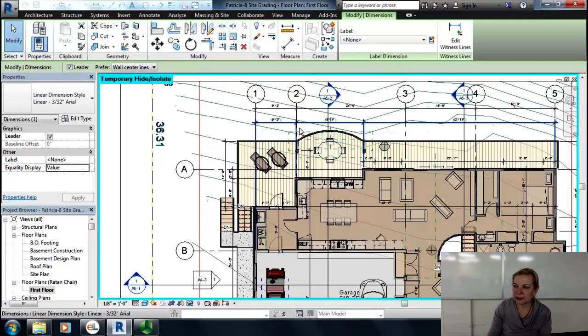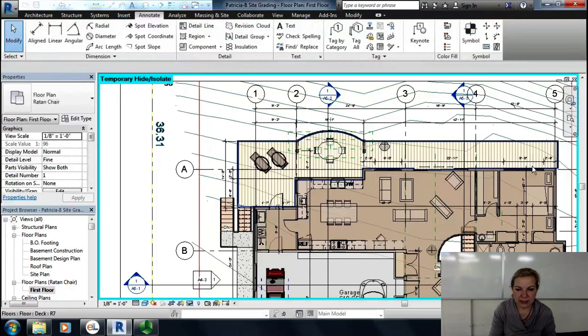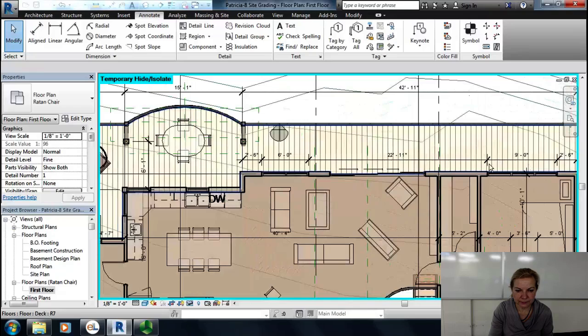If you don't have the grid, you will decide whether you're dimensioning to the outside face of your bearing structure, to center line, or the inside face. Whichever way you do it, make sure that you have the overall dimension on the very outside, then the grid if you have it, then jogs in the wall, and the last string is your openings. So the last string of dimensions is, and I could probably continue with this one, so let's escape. Let's highlight this dimension line.